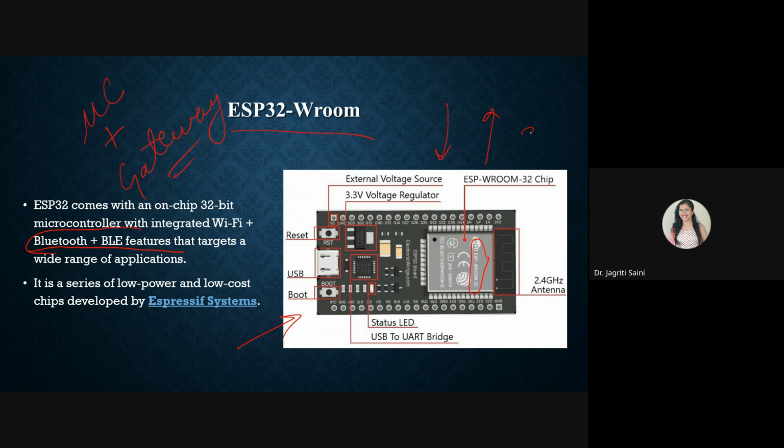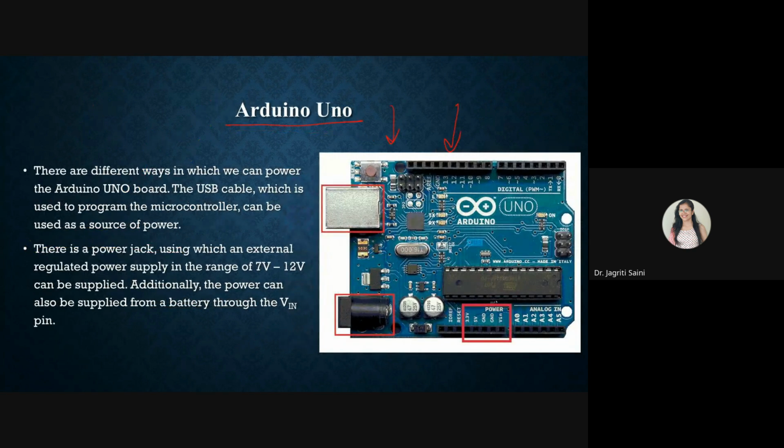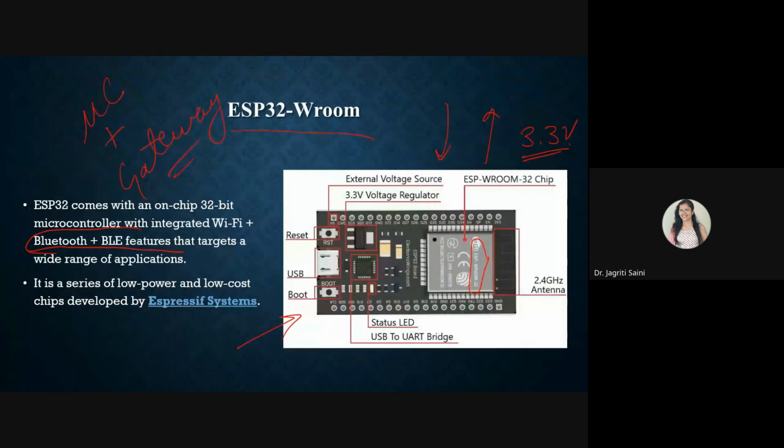This one works on 3.3 volt. This entire chip preferably works on 3.3 volt. However, Arduino, as I told you, works on 5 volt. So depending upon your requirements in the field environment, you can choose a chip.